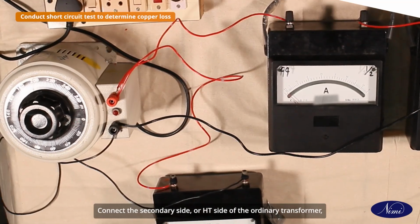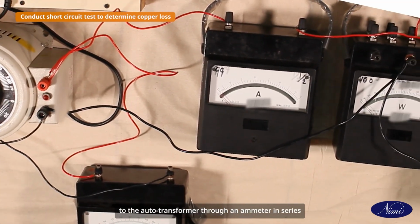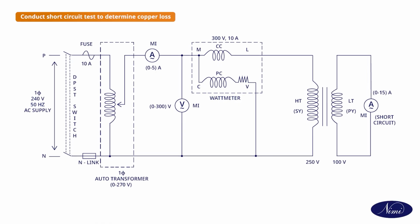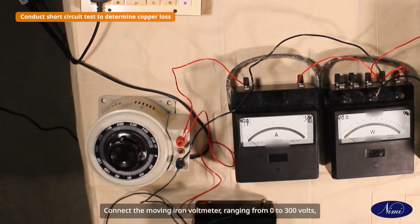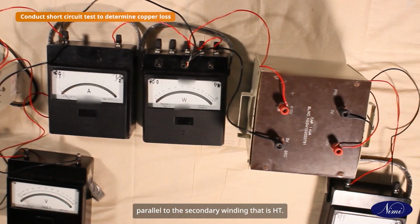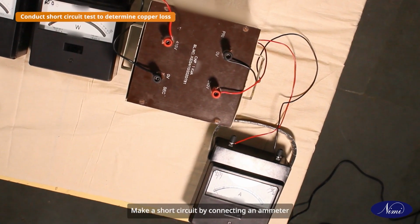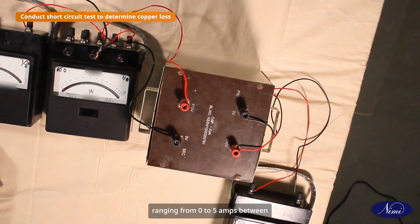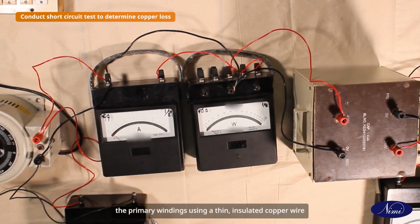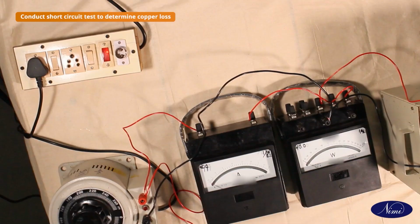Connect the secondary side or HT side of the ordinary transformer to the auto transformer through an ammeter in series and a wattmeter as shown in the circuit diagram. Connect the moving iron voltmeter ranging from 0 to 300 volts parallel to the secondary winding, that is HT. Make a short circuit by connecting an ammeter ranging from 0 to 5 amps between the primary windings using a thin insulated copper wire large enough to carry the maximum load current.